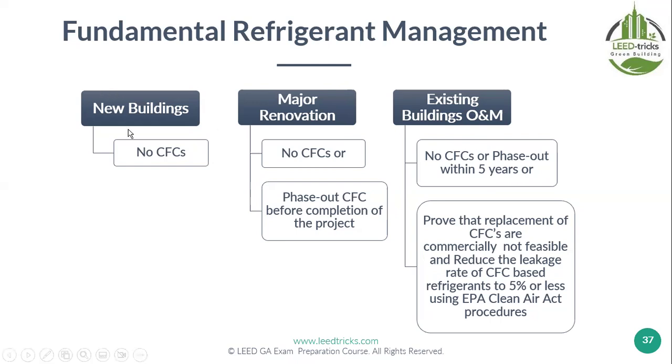For LEED new buildings, no CFCs is a prerequisite, in LEED BD+C or in all LEED. For major renovation, no CFCs also. Suppose I have systems that use CFC. If I have a major renovation, I need to phase out the CFC before completion of the project.